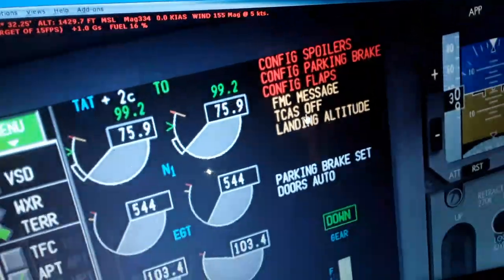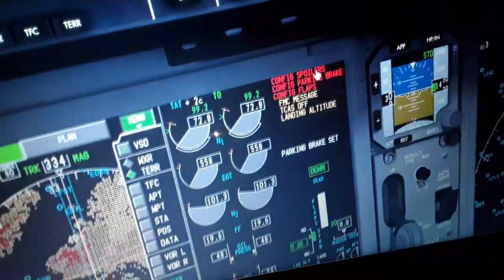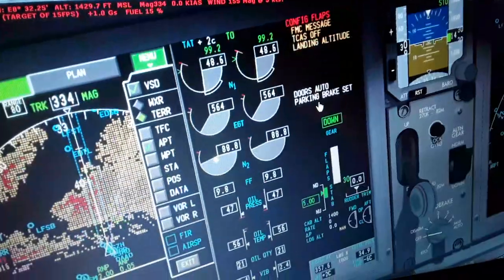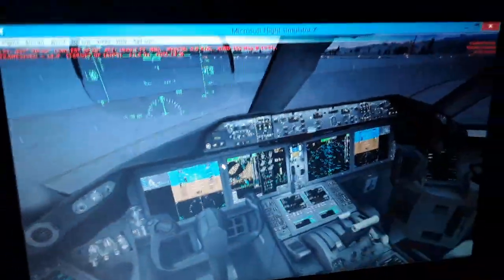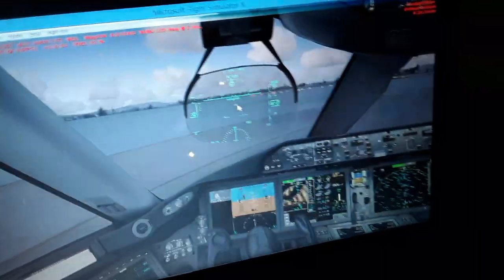So you will see the warning, configure, will not configure for takeoff, like this. You see all the values changed as commanded by the FADEC. The FADEC are the full authority digital electronic control computers. One installed per engine gearbox, dual channel redundancy. One channel fails, the other takes over. Controls monitor display all the engine data you see in the upper and lower EICAS.